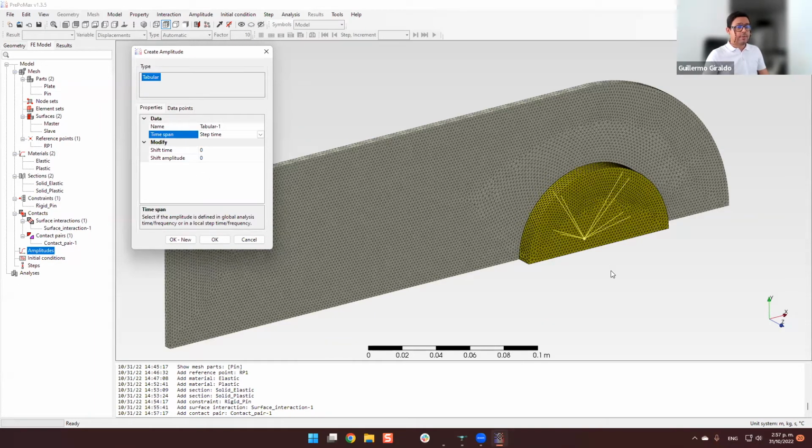So if I apply the load that I want to apply to this point suddenly, then the changes in the deformations or the changes in the state of the model can be so big that the solver won't be able to find this solution because the change is too large.